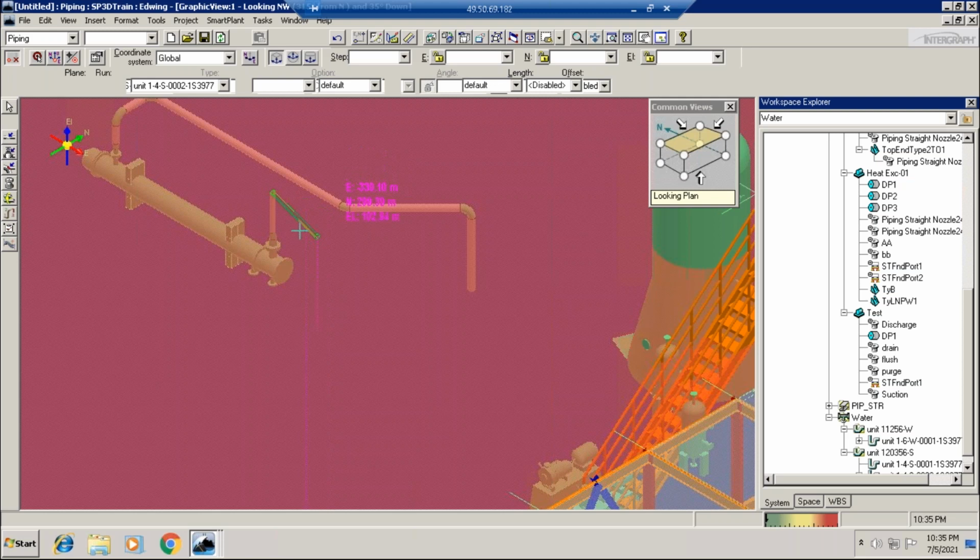Okay, so how do I know now if I... Also, you can use the direction. We are using middle click for locking the planes, right? Wait, Edwin, one thing. So you see here that straight line is coming up, right? So you can lock at this point so that it will move in this east-west direction only. So middle click to lock the axis.